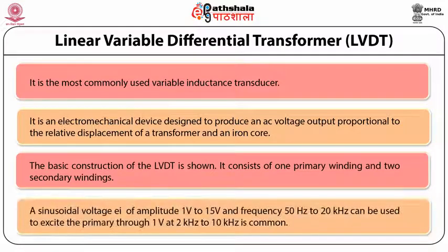So a sinusoidal voltage Ei of amplitude 1 volt to 15 volt and frequency 50 Hz to 20 kHz can be used to excite the primary, though 1 volt at 2 kHz to 10 kHz is common.